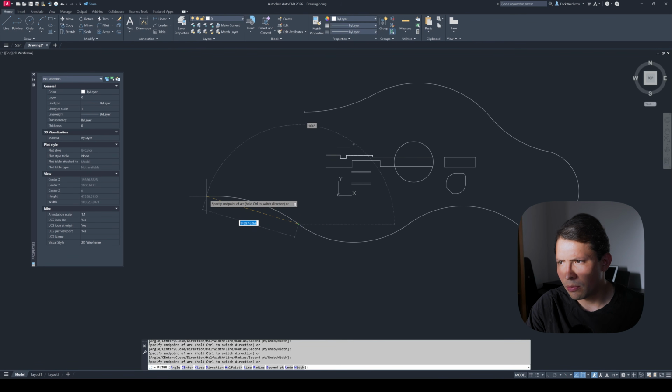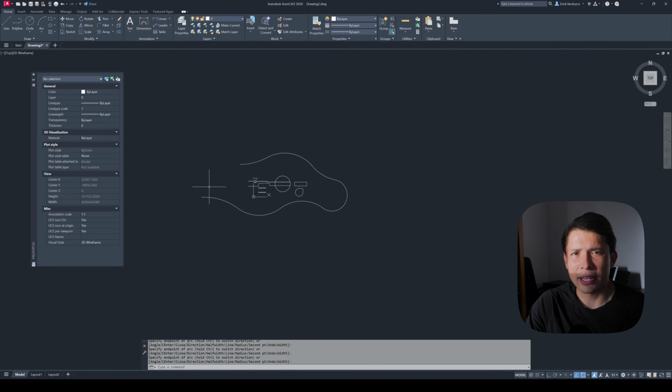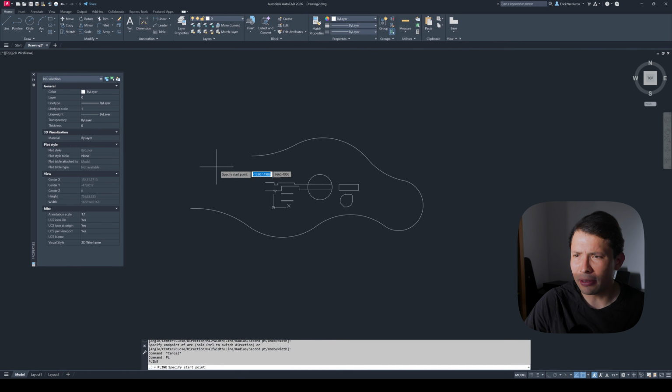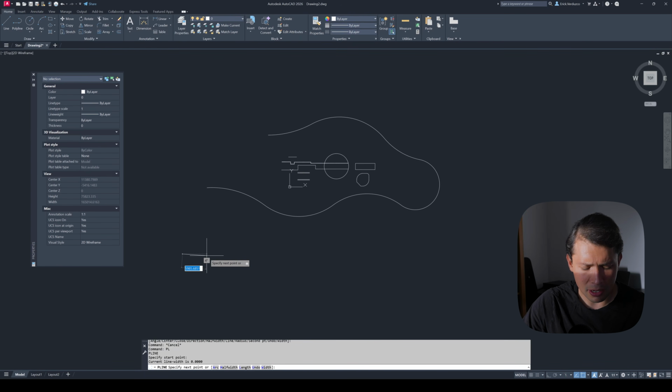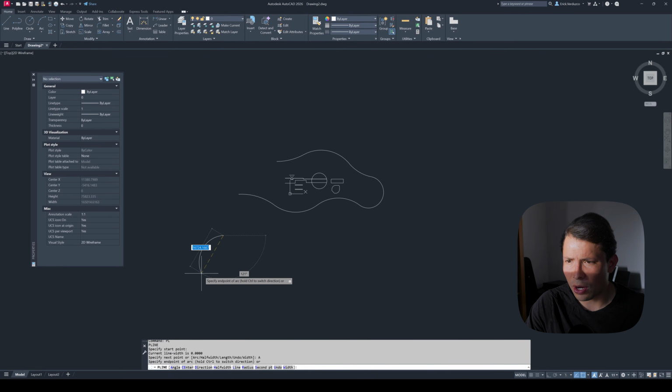and somewhere here. Now, what happens if you want to create an arc that is irregular and you want to choose exactly what's the radius of each? So for doing that, I'm going to repeat the polyline command. And then I'm going to start here this time. And I'm going to click arc again. And then once I am inside arc, I am going to choose the second point, because as you can see right here is quite limited.